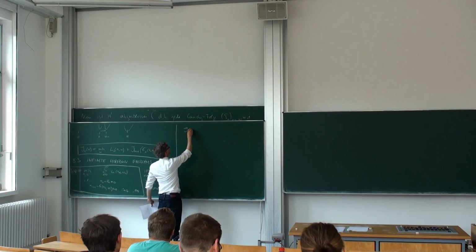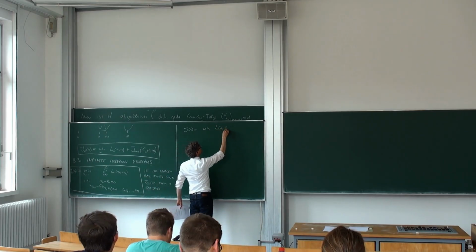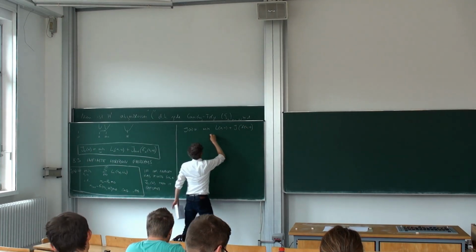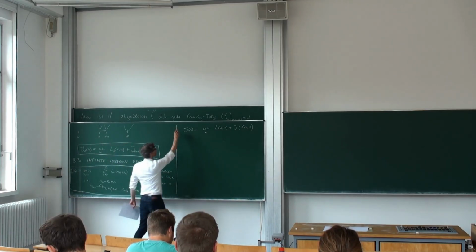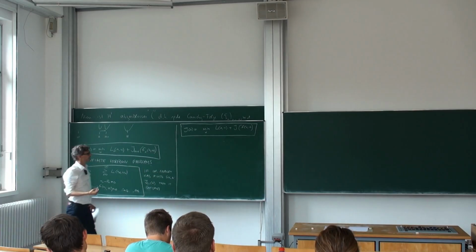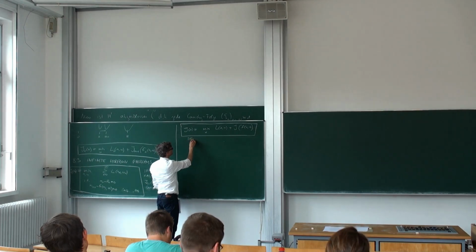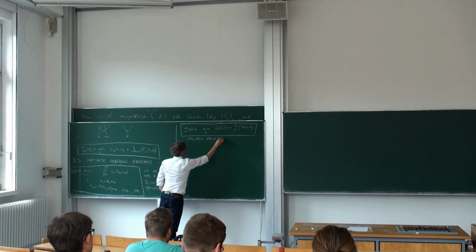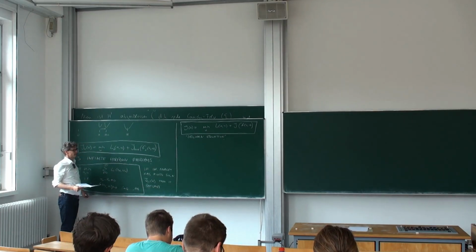The equation is that the J of x is equal to the minimum of L of x, u plus the same J. This is now the difference to before. Minimized over u. So that's it. It's just a stationary equation now. You could think it's like a fixed point equation for the function J, and this is called the Bellman equation. And that defines the optimal cost to go for an infinite horizon problem.